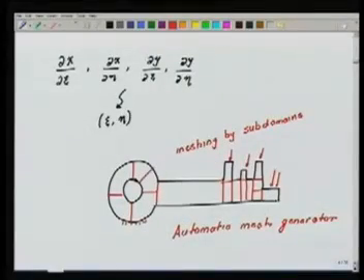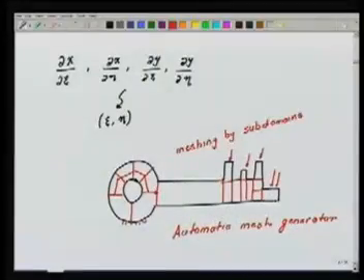In most of the standard automatic mesh generators we have the feature of defining subdomains, and there we define the subdomains and then do the meshing by subdomains to get a pretty good looking uniform mesh, such that the continuity is maintained, that is the nodes from the two sides should overlap. On the common edges the nodes should overlap.